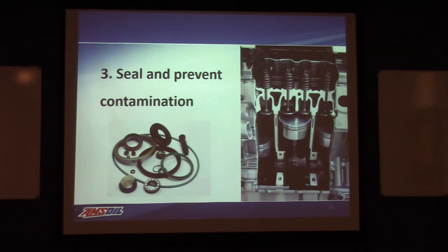Seal and prevent contamination. That's kind of a twofold issue. First of all, we know that within that engine, there's going to be a lot of dynamic situations in which sealing is important between the cylinder liners and pistons and rings and that type of thing. Oils have to be of the proper viscosity to minimize transfer in those areas.